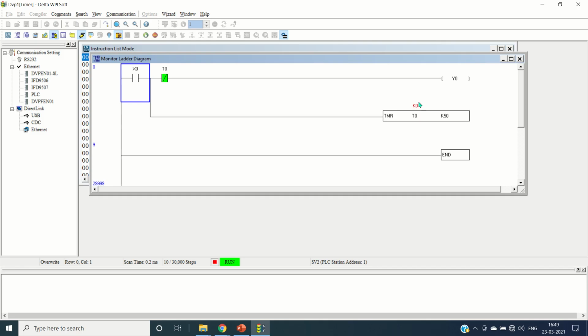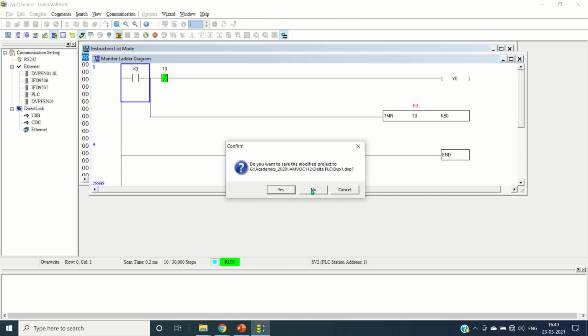The timers which are unable to keep track of the time, whenever there is a power failure or some other operation or the particular situation at the input goes wrong, and do not hold the time, such types of timers are called non-retentive timers. Non-retentive timers means they do not retain the value. The timers which can remember the particular value at which the input condition of the rung was wrong or there was some power failure, we call a retentive timer. So let us now get back to our actual discussion.